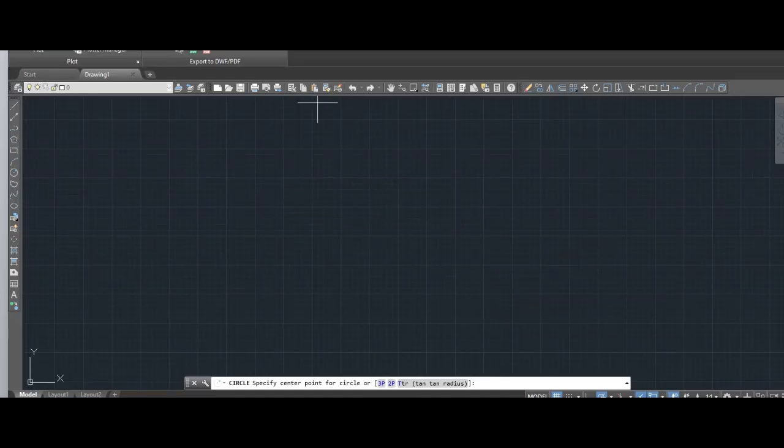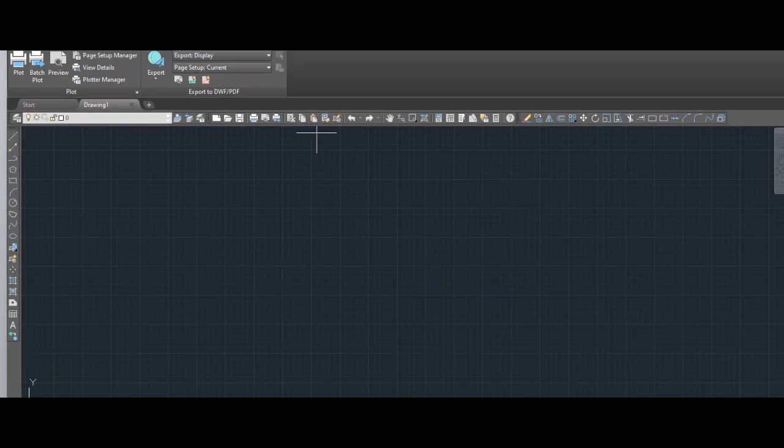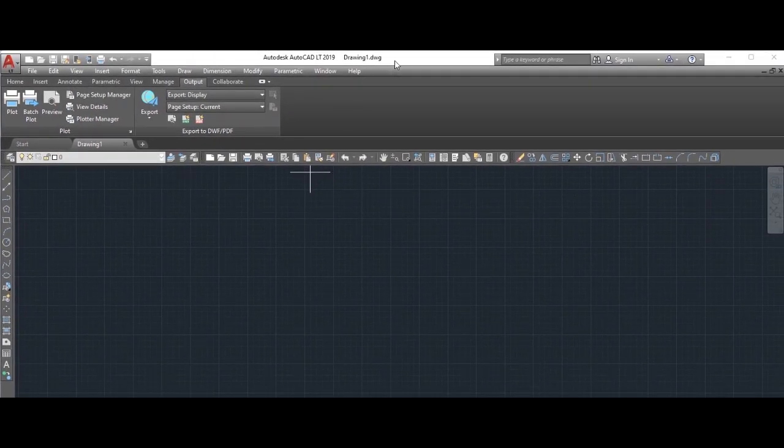So let me bring out the AutoCAD into the recording menu. So we're here right now. The first thing we're going to do to draw a flange, I'll pick the circle tool. I pick it here, I come to any position, let me look for a good position here. I put it at this point here.